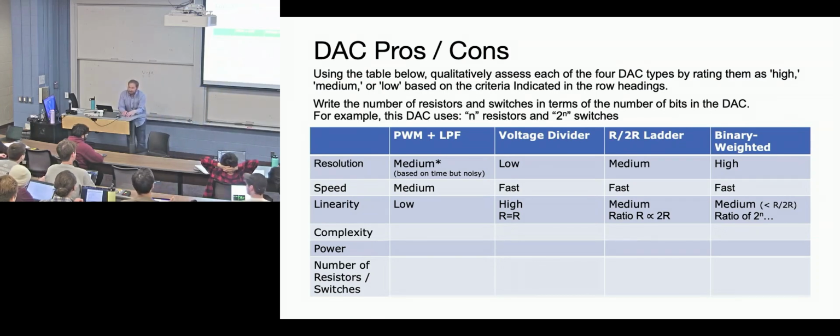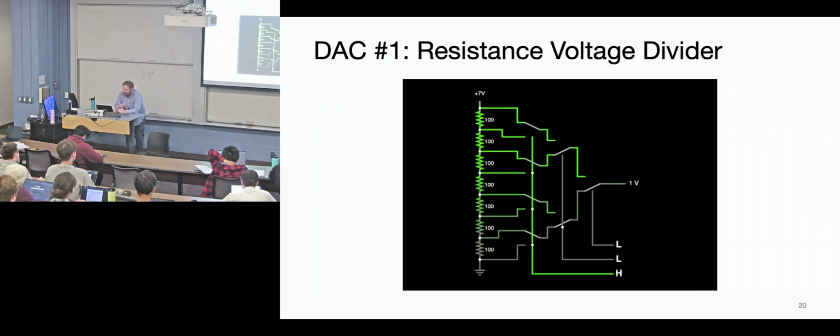What is linearity? As I go from one value to another value, what's the likelihood that the step size is going to be the same? Say it again. Okay, clearly I have holes in my teaching. Fantastic. Here we see resistors. What happens if one of those resistors was 99? Then I'd walk through and I'd have this misstep in my DAC outputs. I'd want some value and it would be a little bit off. So that's what we mean by linearity. It's not a linear step.